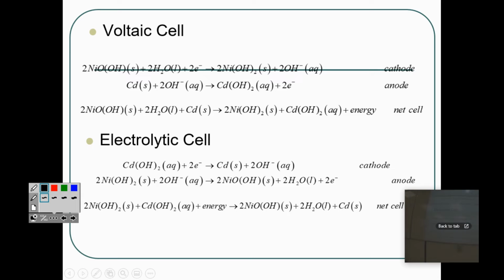Now, as I said, there were a lot of problems with nickel cadmium batteries if you didn't drain them. If you didn't drain the battery, it wouldn't fully charge again. It had a memory. So if you recharged it when it was at 25% and you did that a lot, you would only get 75% of the battery life after a while.